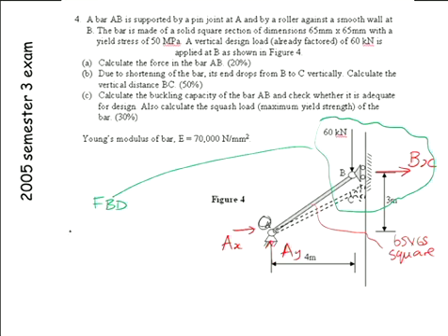And in that free body diagram, I draw the forces I know, the forces I don't know. So in this instance here, we're using the method of joints not to solve for an internal force, but to solve for a reactive force. Method of joints just applies to forces. Method of joints doesn't say it has to be an internal force, it has to be a truss. Okay? That's why I'm saying we give it this wonderful name, the method of joints.